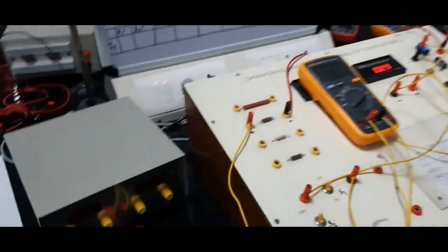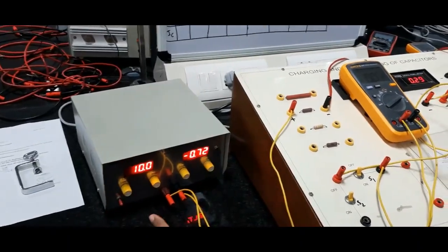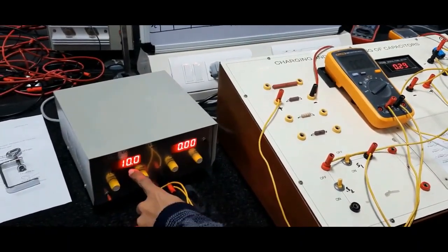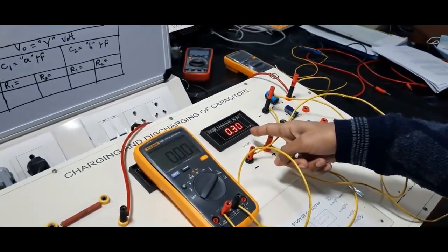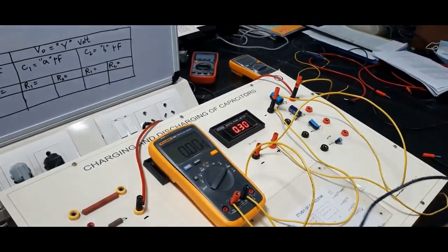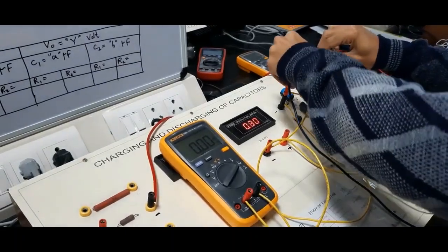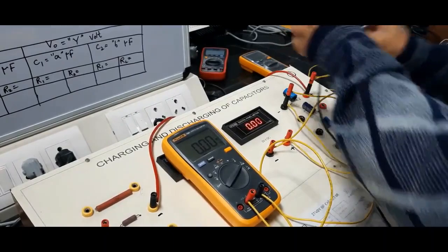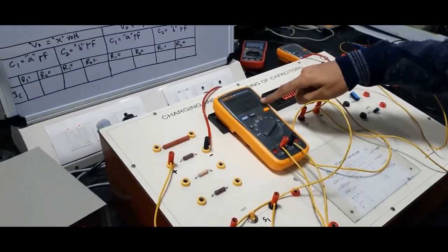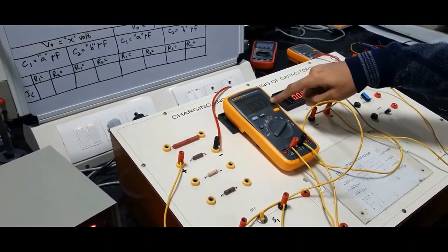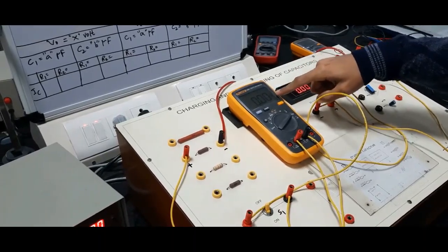Now let us switch on the voltage supply, and for this demo measurement, we fix the voltage around 10 volt. You can see there are some small fluctuations in the VDC voltmeter, so we will first short it using a wire. So it is now a zero reading. Moreover, I want to mention that we are going to measure the DC current, so I have fixed this setting to DC. You can change it between DC and AC by pressing this yellow button. I have fixed it in DC.